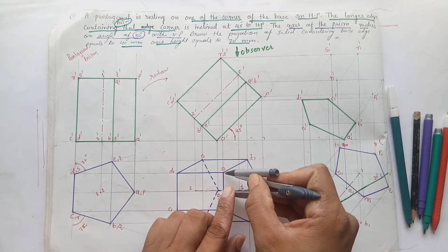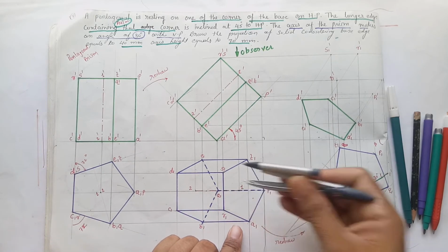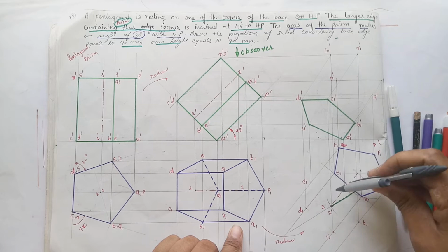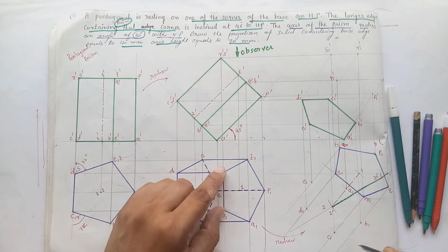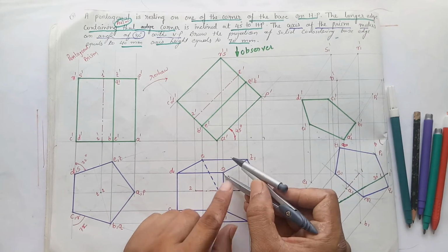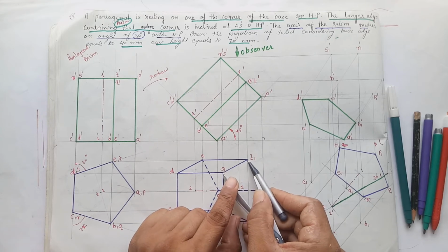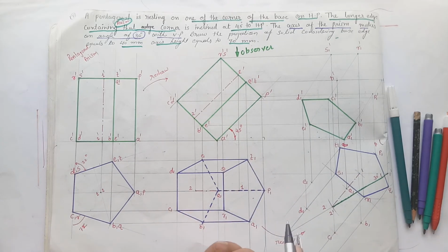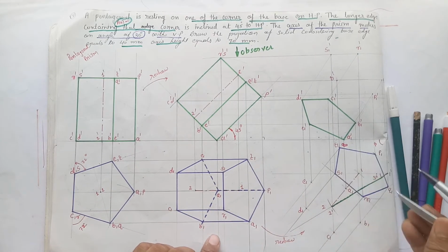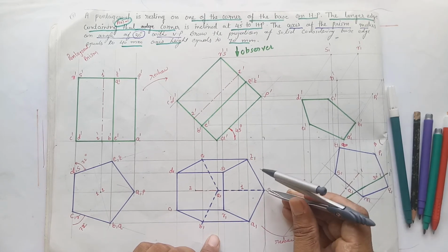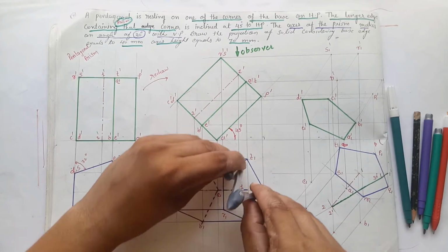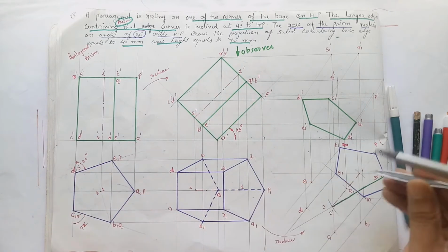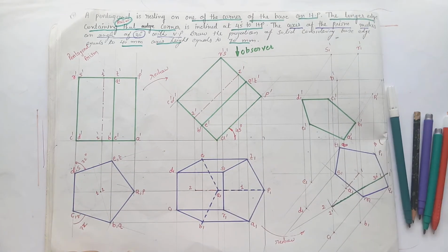After drawing the line perpendicular, measure this distance, mark this length as R. After marking SR, let us mark T and Q. So give an arc from S, R. Then after measure T and Q from P and give an arc. So draw the top face.